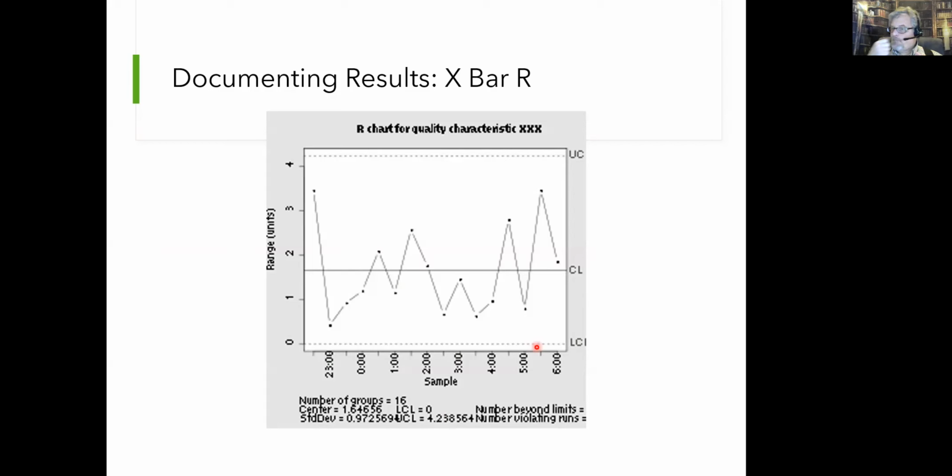Everything's good, right? So this part can be up to an 1/8 of an inch long, but it can only be a 1/16 of an inch short. You don't want it too short, it's a problem. So those might be your upper limits.